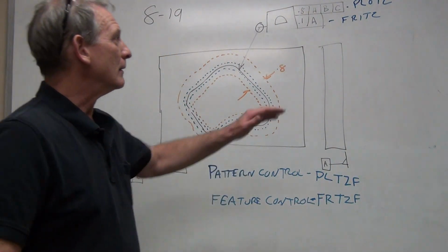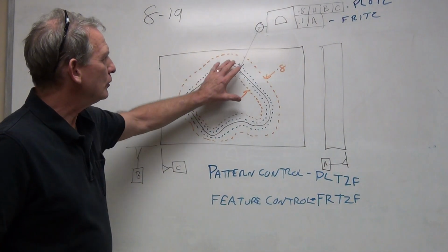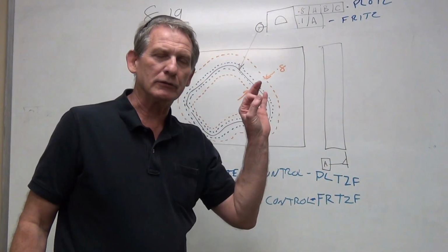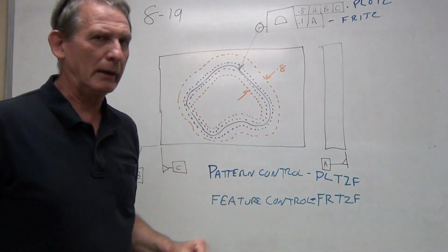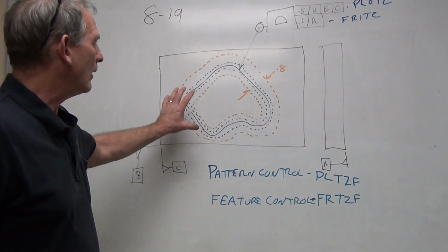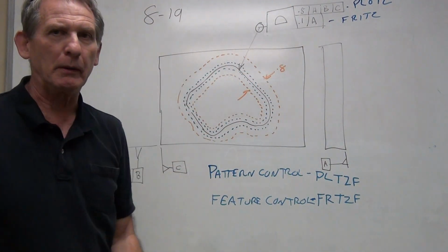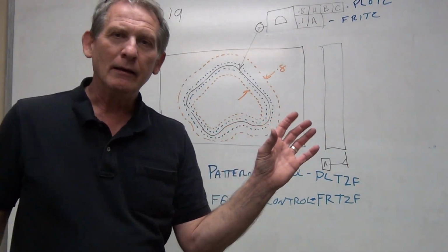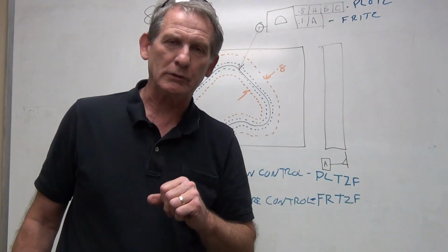And then in the upper feature control frame, the plots, we say that if you make this hole with all these different features, if you make this within this tight blue tolerance band, we can allow that whole tolerance band to move around within the orange boundaries. So in other words, cut the hole precisely, and then we won't have to worry so much about where it is in its actual position.